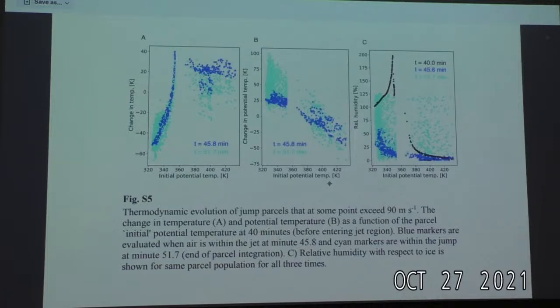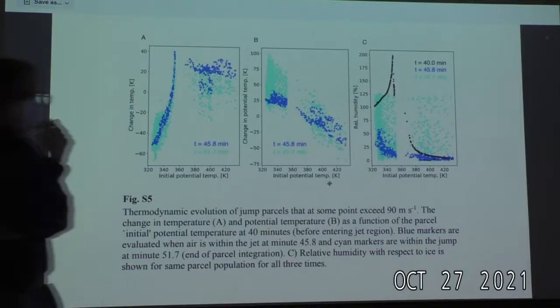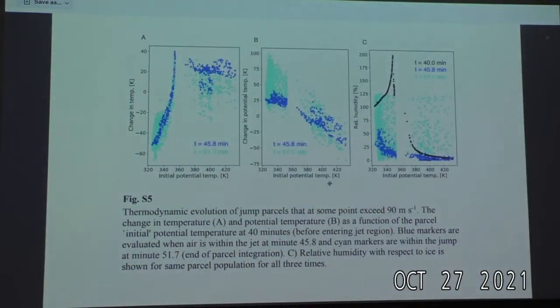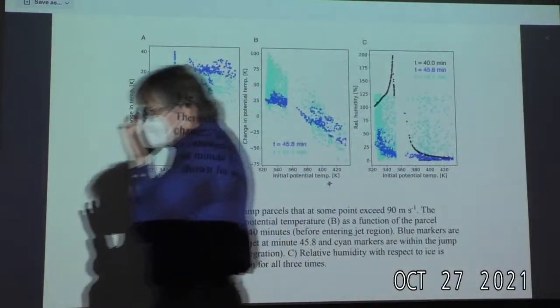So it looks like the simulation is stable, but you did bring up CFL as a potential issue. You said 150 meters per second winds, 50 meter grid, and a third of a second time step. No, 100 meters per second, not 150. I thought you said your maximum was 150. No, 100. I think our maximum was 110. Have you cut the time step in half to see if you still get it? I know that's an expensive experiment.